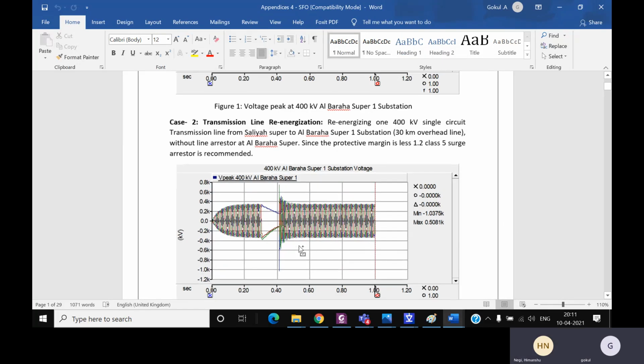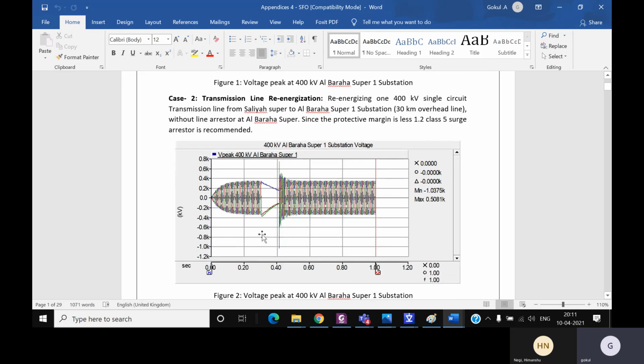Up to 0.23, the system is just 400 kV. But I'm going to open the breaker, and there will be some flux in my system, or some charges will decay and it goes to zero. But within 100 milliseconds, I'm going to re-close the circuit breaker. If I do that, there are some possibilities. It may go up to 1000 kV.